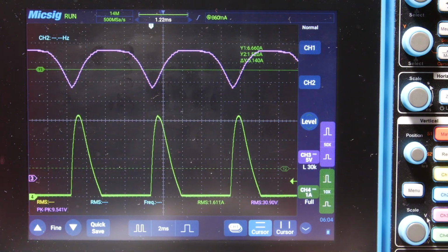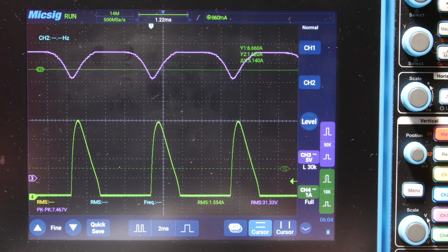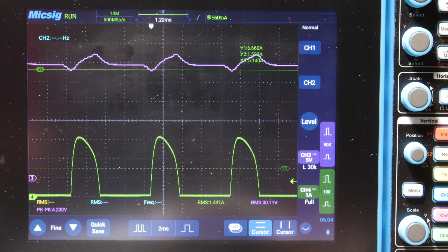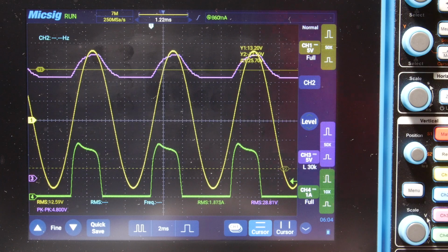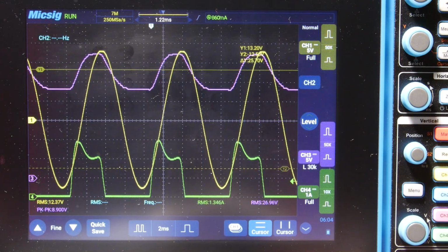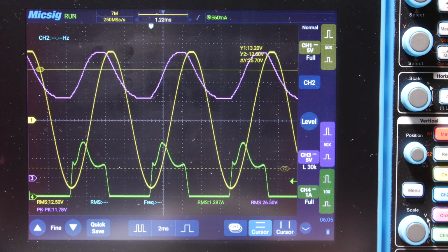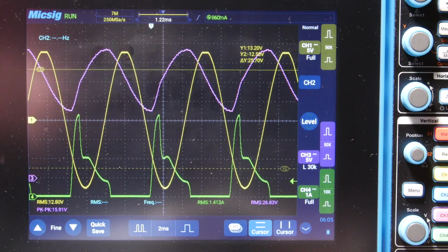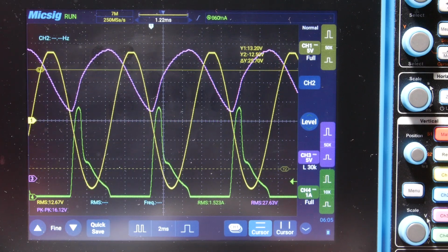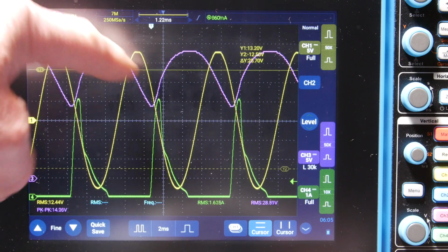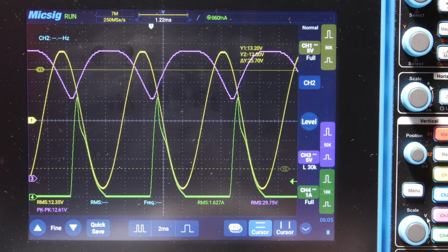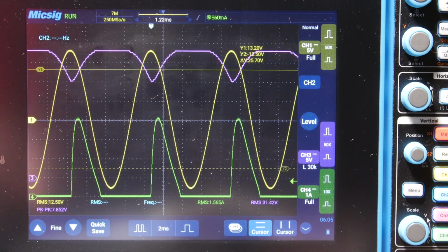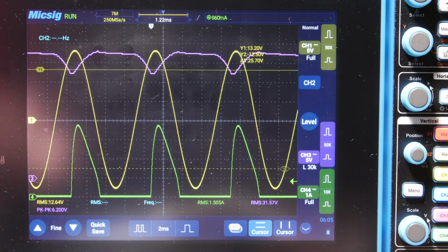Now it's kind of changing because we're at the same frequency as the line frequency, but we're not. Here, let's look at the output voltage. See how the output voltage is kind of drifting? And this purple waveform is the current charging our capacitors, our rectifiers, but we're not in sync. So now look how it's starting to clip here. Our 120 hertz from our generator is not synced up with our AC power coming in. So maybe it's going slightly faster.